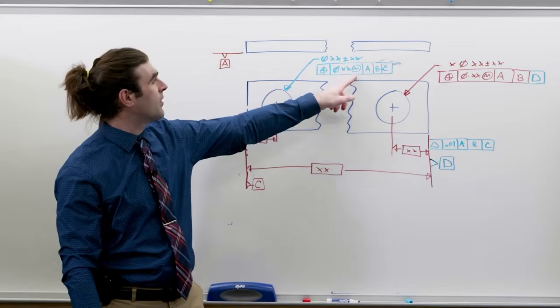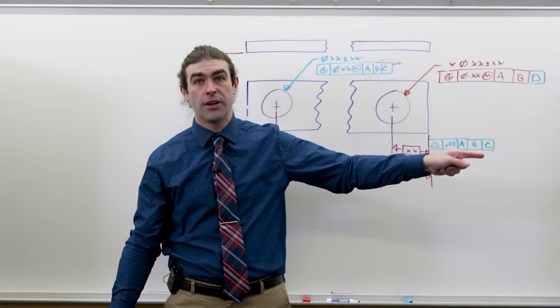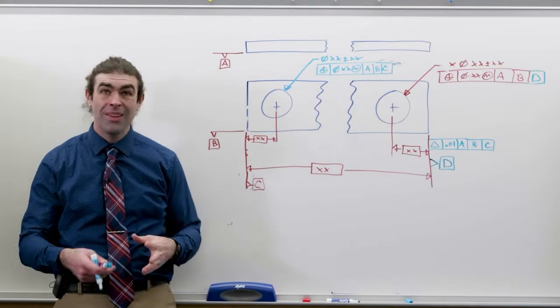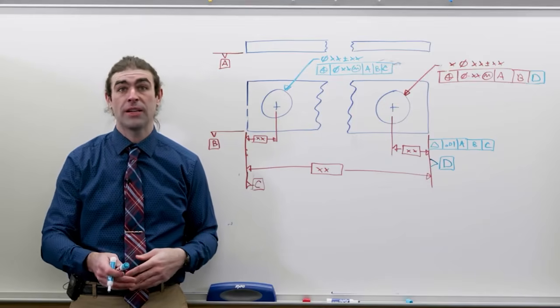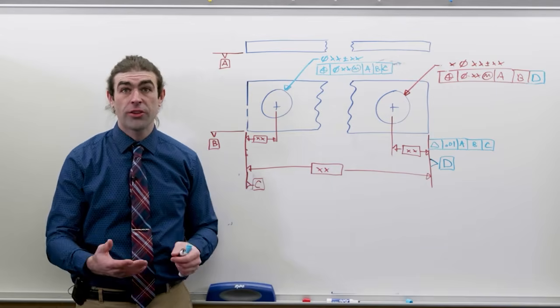So this is a different datum reference frame than this. It requires a different inspection setup to make that happen. If you're programming a CMM, probably a little bit easier, but you still have to remember to punch in the right stuff. So that's it for this first talk about datums.